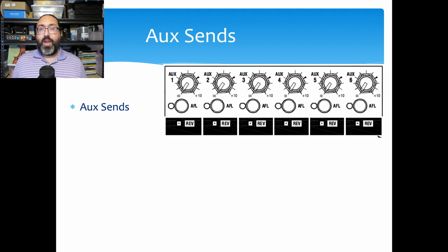There are other consoles that have different marks, and there might be times in your career that you don't want to send that much signal to X speaker or X output. As for instance, if you are ever working a political event that requires one of those line out boxes, a lot of times you have to attenuate that signal a bit. Otherwise, you will blow out the inputs of every single one of the press people. Now, as much as part of me thinks that's a little bit funny, you want to make sure you back off a little bit. But for the purpose of this class and for this console, we set it to that triangle.